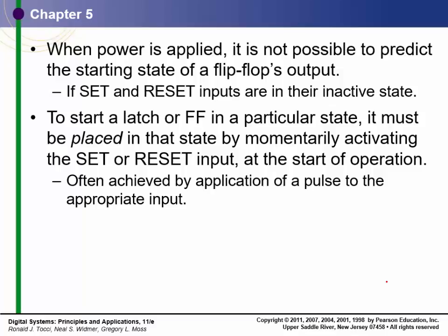Usually, like I said, a power on reset. The most common power on reset is: here's your power switch, here's a resistor, here's a capacitor. When you first power it on, this goes to your reset. That capacitor looks like a short, and then as the voltage ramps up on the capacitor, it then becomes a high. Once it reaches 3 volts, it's a high, and this creates an active low reset right there. And we'll see that most of our resets are active low.